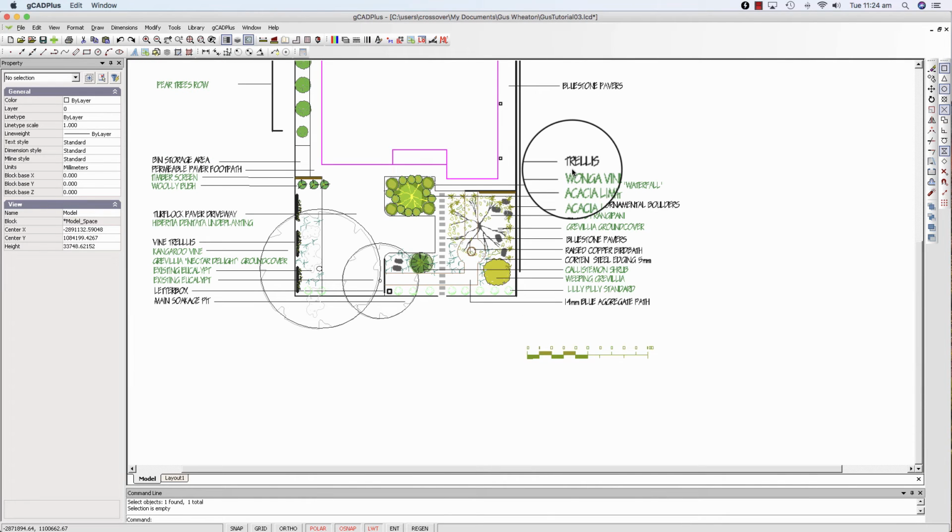We can now work a little more easily with CAD Plus. This design in model space works quite well. We've now got control over our object snaps. And notice in the panel on the right that just those that we turned on are on. And if you look down here in the O snap button, if we click there, that turns those snaps on and off.